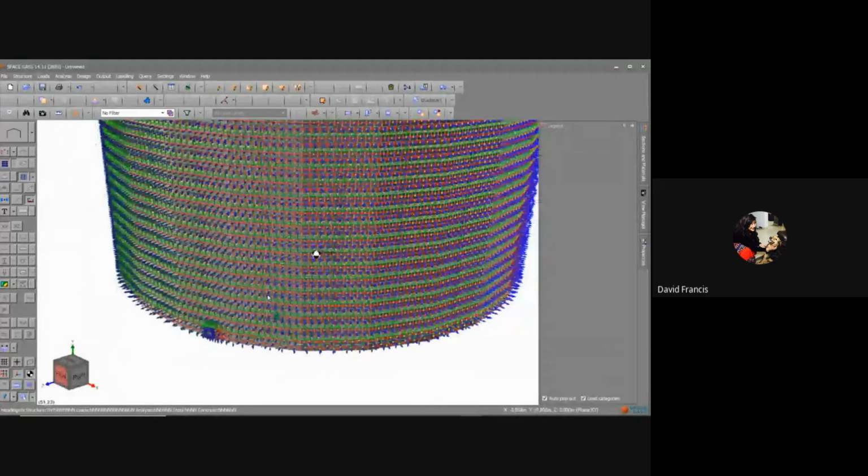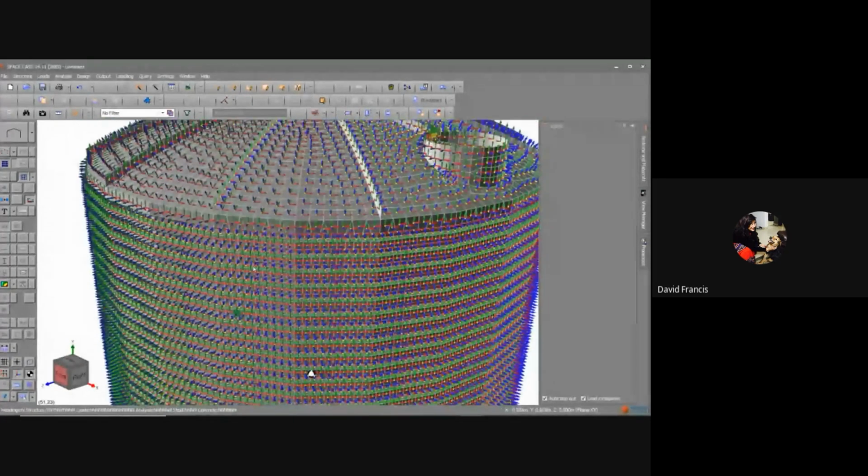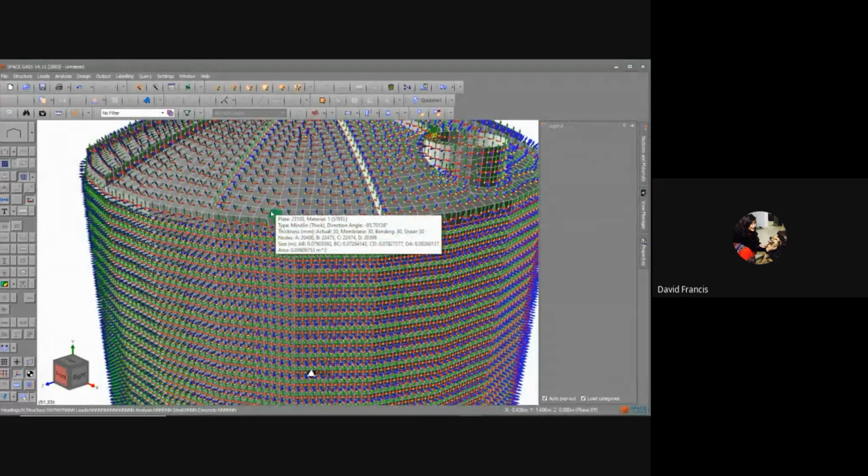And this is really useful because it leads to the fact that we can show plated structures, and we can show stress diagrams, we can show areas of steel. If it's a concrete slab, because the direction of Z is the vertical and X and Y follow the global X and Y, we don't have to worry.